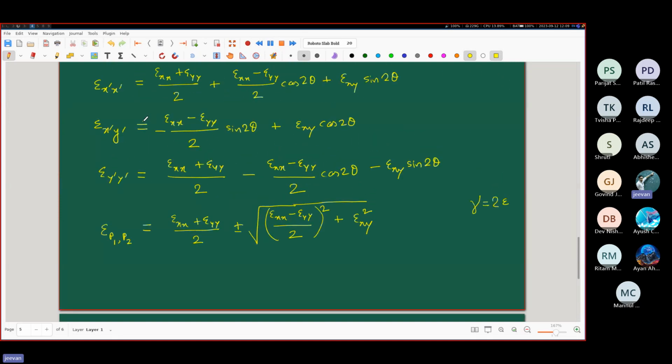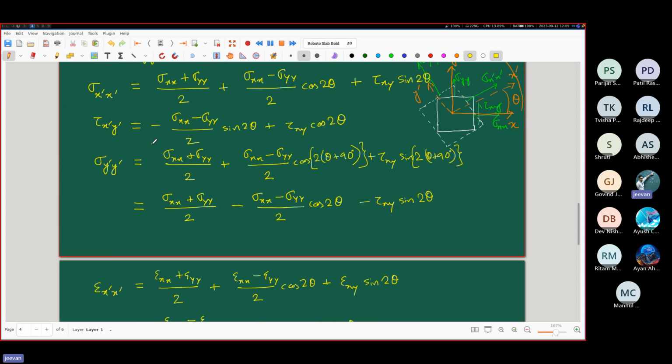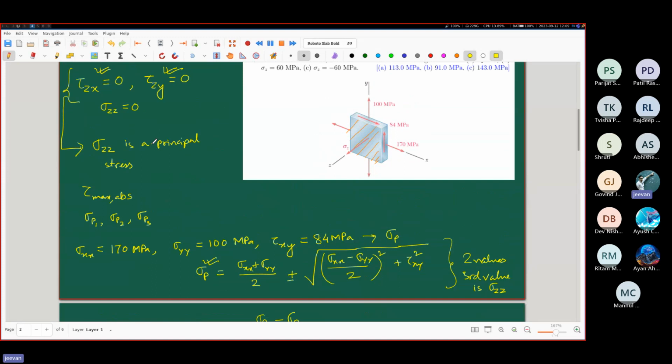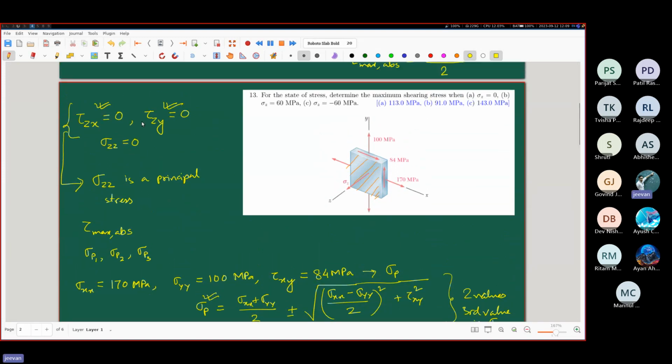When we were talking about the stresses, we talked about something called plane stress. For plane stress, we said that sigma zz is equal to 0, sigma yz equal to 0, sigma zx equal to 0. That was a plane stress situation parallel to the xy plane. Please do not make this mistake: you may as well have a plane stress situation for the x plane also.